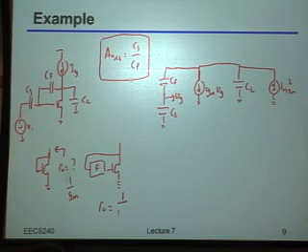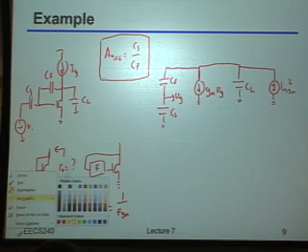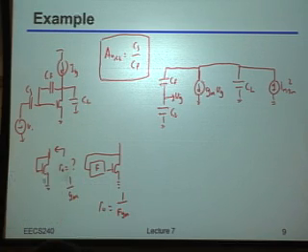That's absolutely correct, but how'd you get it? What's the intuition behind that? Okay, yeah. All you basically said was that the reason the first thing gave you 1 over GM in the first place was that if I had a movement on the drain, I had GM times that drain voltage of movement of current coming out of it.